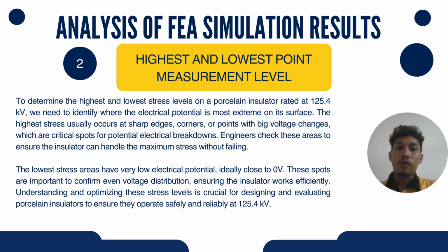Okay, we go to the next analysis, which is the highest and lowest point measurement level. To determine the highest and lowest stress levels on a porcelain insulator rated at 154 kilovolt, we need to identify where the electrical potential is most extreme on its surface. The highest stress usually occurs at sharp edges, corners, or points with big changes, which are critical spots for potential electrical breakdowns. Engineers check these areas to ensure the insulator can handle the maximum stress without failing.